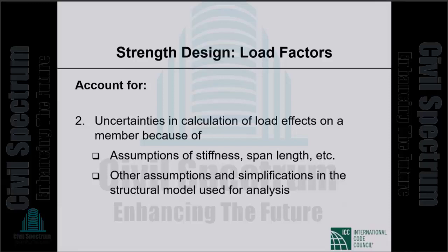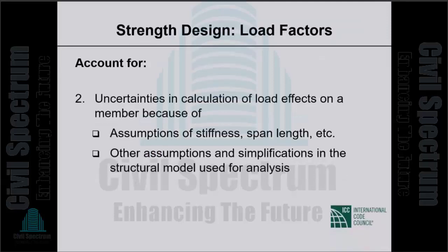In that analysis, we have to make assumptions of stiffness, span length, etc. Other assumptions and simplifications in the structural model used for analysis. There are uncertainties involved in all of those. We assume a particular stiffness, it may be different. This is why we need these load factors.